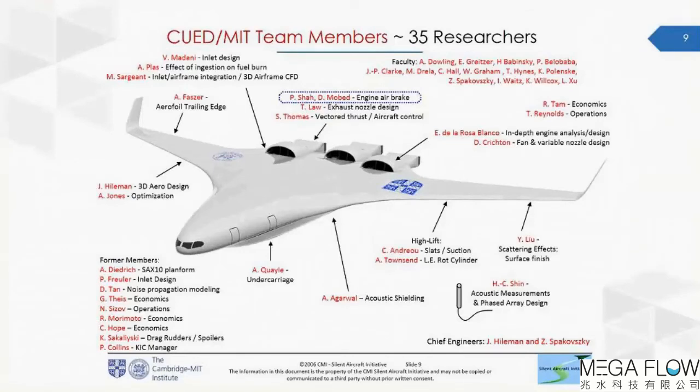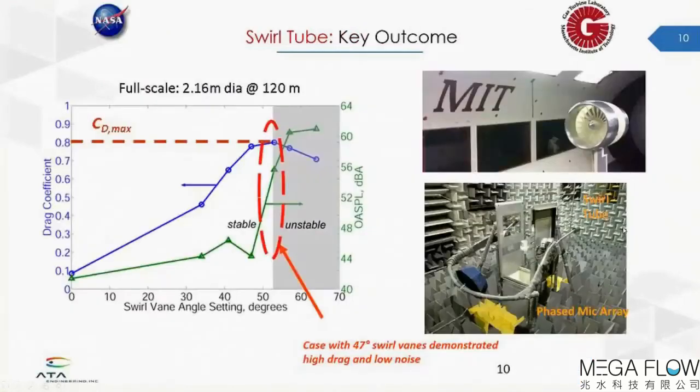And at that time, the need for quiet drag was identified as a potential low-noise enabler to an aircraft that would be quite slippery on descent and approach. We called that idea an engine air brake, though at the time we hadn't quite envisioned how we would be able to integrate that with an engine. But as part of that work, we came up with the idea of swirling the exhaust flow. And since engine integration would be quite complex, in my PhD work, which was sponsored by NASA, we demonstrated the idea that a steady exhaust flow emanating from a nacelle with swirl could potentially give quiet drag.